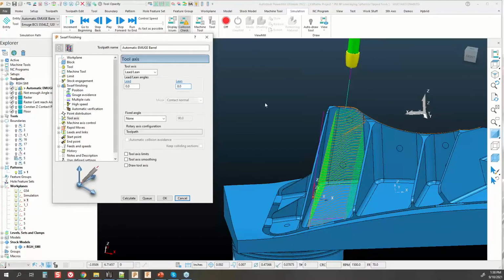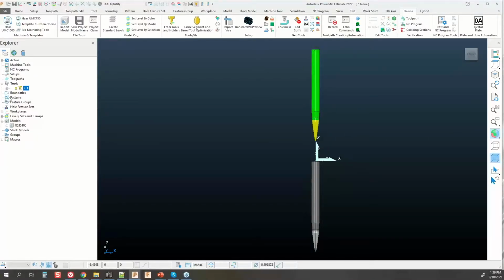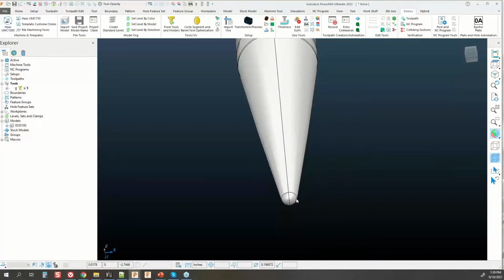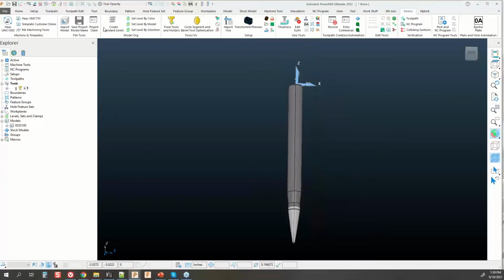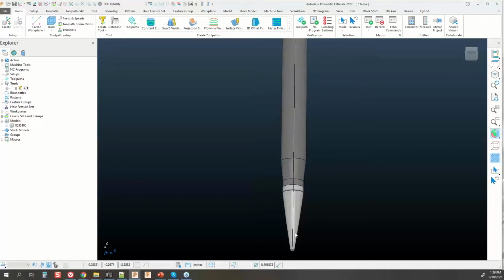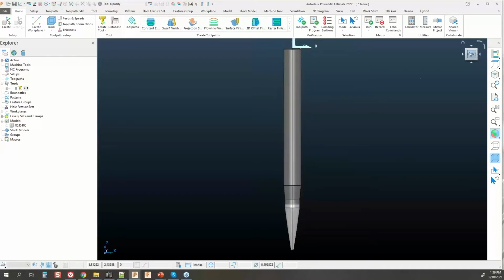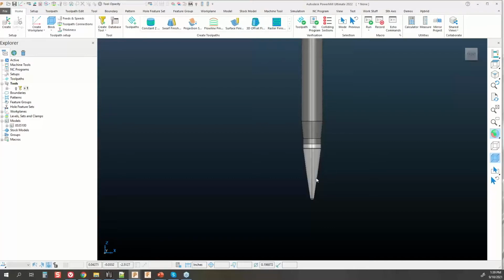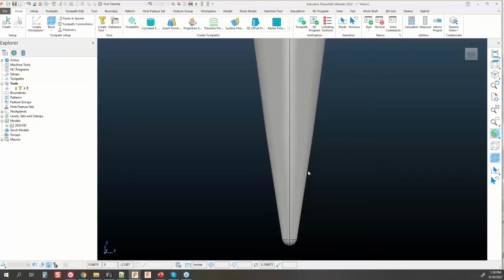Now, figuring this out, I'll jump back over to my other session of PowerMill and look at that pattern profile real quick. I'm going to spin a profile from this tool real fast, and I'll just use the geometry. I'm not going to have to place it in place or anything like that. What we're looking for is the contact that we're going to be on our surface. It's not always straightforward. A lot of times what you'll get as the contact is the average angle right at the center of the cut. If we're reaching down inside to a deep pocket, we may actually end up being more towards the end of the tip of our spherical tool when we do this.